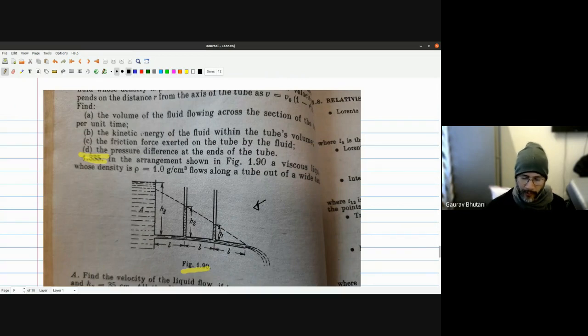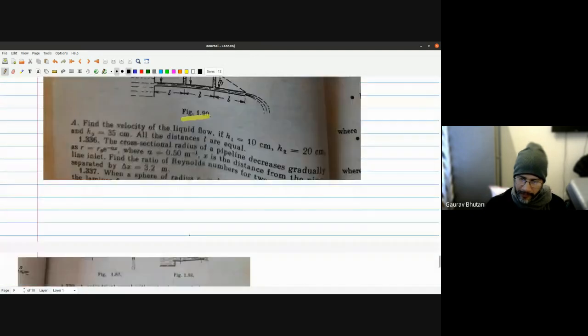As the flow happens through a pipe, it loses some energy because of viscosity, and then you can see that the static pressure that you're measuring using some sort of a manometer is much smaller.